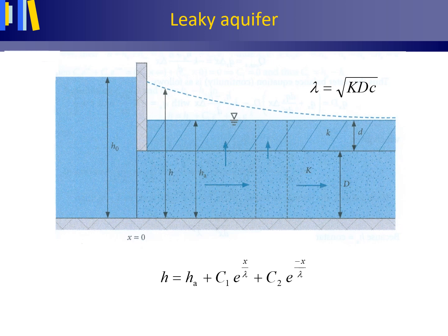The main equations in determining the shape of the potentiometric surface of the aquifer are, as to be expected, the continuity or water balance equation and Darcy's law, the Darcy equation. These are combined for this column or rectangle. I will now only highlight the ingredients, so to speak, as some of these will be most useful when making hydrological calculations for leaky aquifers.